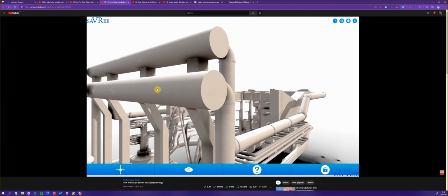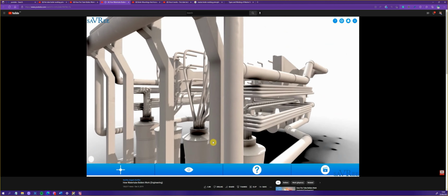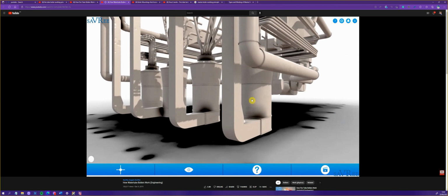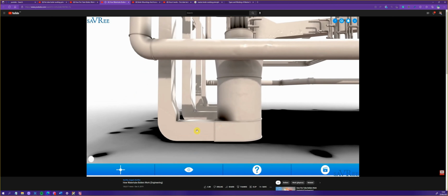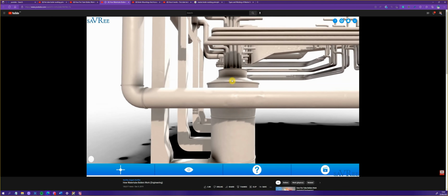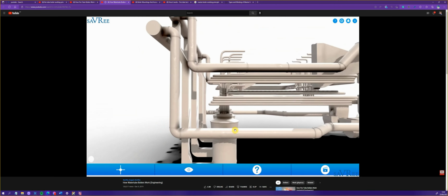It's actually going to come into this duct here, and then it's going to be fed downwards to our cold pulverizer. Goes in at the base, and then we will use that air, which will be blown up through the cold pulverizer, and then along the tubes and into the furnace.